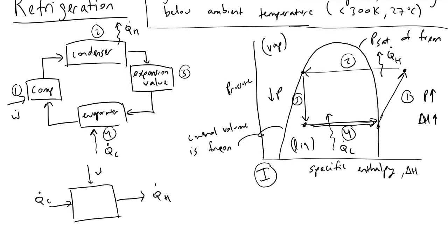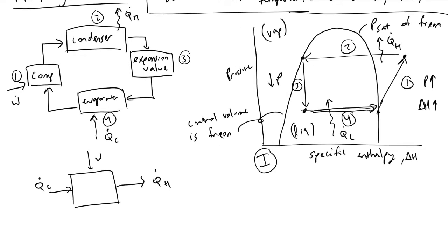And so getting back to our energy balance on the Freon, you can quite simply say whatever's coming in must be equal to what's leaving because energy is conserved, and therefore we can say that QH is equivalent to QC plus whatever work you're performing on your Freon over time. And so in a car, this is the work due to the belt that's driving the compressor in the engine bay. And so these are the quantities you get.